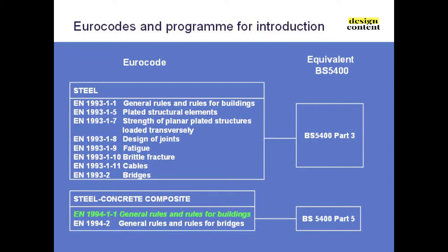And that was really because Eurocode 4 Part 2, in its first incarnation, which was a bolt-on, was impossible to use, really. There were too many cross-references because it had to cross-reference to the loading parts, to Eurocode 2, to Eurocode 3, to the other part of Eurocode 4, and I think there was one clause which contained, I think, 6 cross-references, and it was just unreadable. And so the decision was made to separate that part out, and I think that was a good decision, and in many ways it's a shame that we didn't do that with the other Eurocodes, because it's a much easier document to read without having to flick to another one to see what's changed.